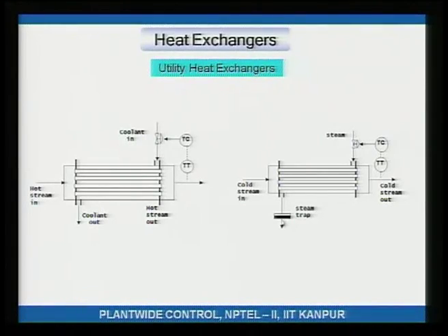Okay. By the way, there is a steam trap shown here. What is a steam trap? Well, a steam trap, as the name suggests, traps steam. Suppose this valve is open, then you will lose precious steam. Steam is precious. Okay. So, what a steam trap does is essentially let steam condense. Steam loses heat, therefore it condenses, and once a sufficient amount is condensed, the trap would open, let out the condensate and then close again. Okay.